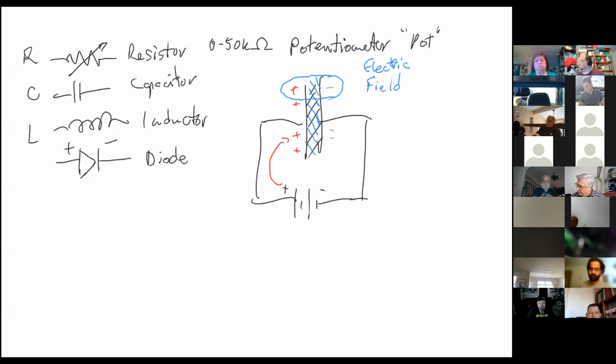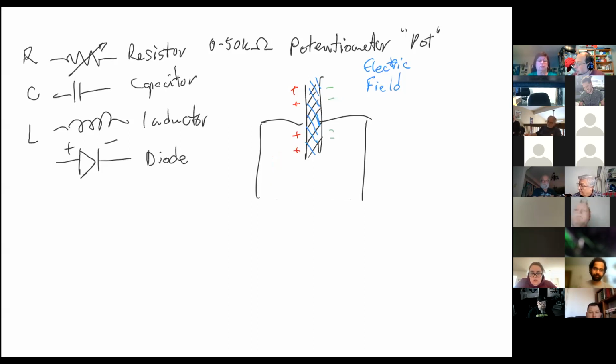So it's essentially creating a fully charged thing that's now storing energy. So a capacitor stores energy in its electric field. Now, interesting about a capacitor, what would happen if I took the battery off? What would happen to the charge? It'll stay there. It's just going to stay there. It has nowhere to go. Now, what would happen if I do this?